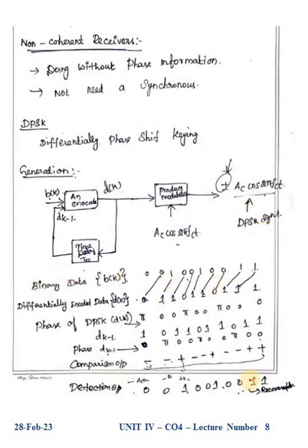Let us consider this example. This is binary data represented as bk, and we give the input 0 0 1 0 0 1 0 0 1 1. The differentially encoded output from the encoder is written as dk. For dk, first the signal is 0, then one unit of delay is introduced for every bit.